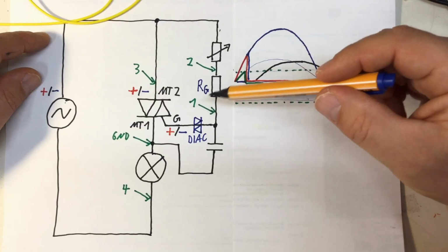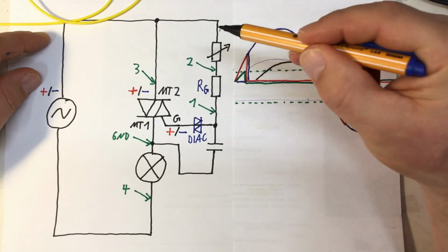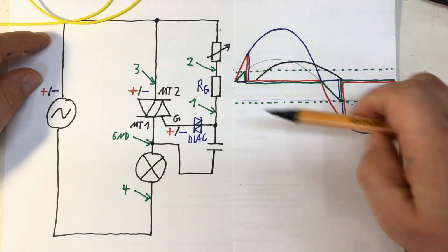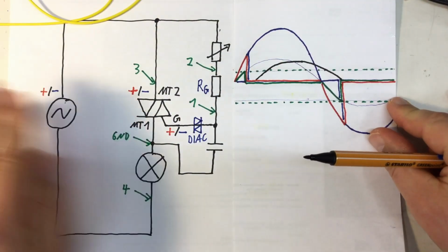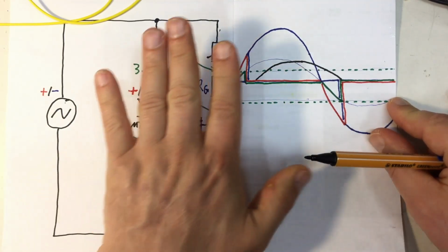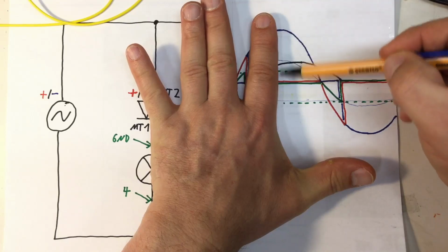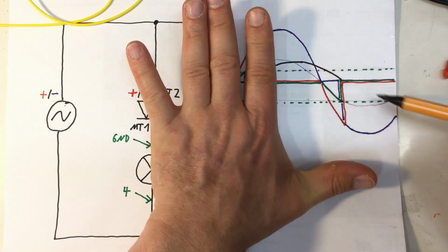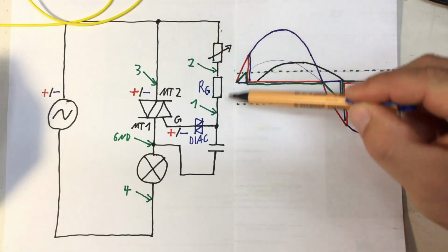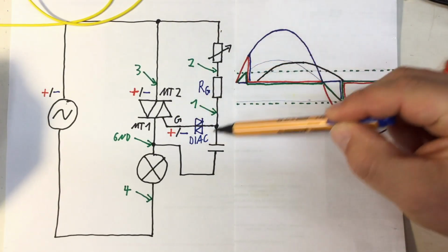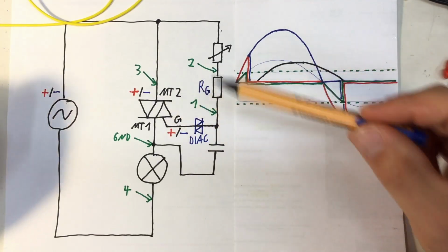But what happens if my potentiometer is turned down to 0? And this is in some mains appliance, and we plug it in right in the moment where we are at mains peak voltage. Then we would get a short, very high pulse into the gate.